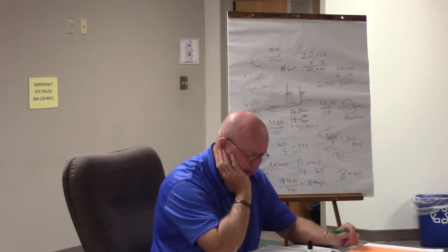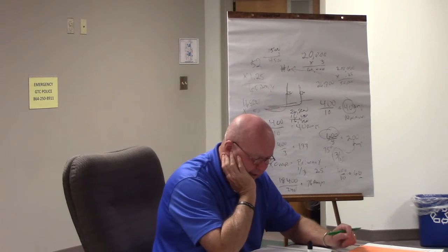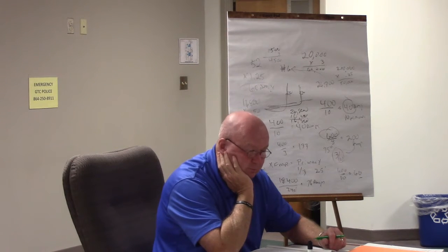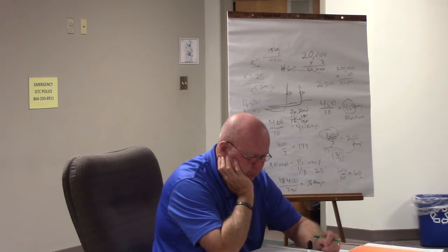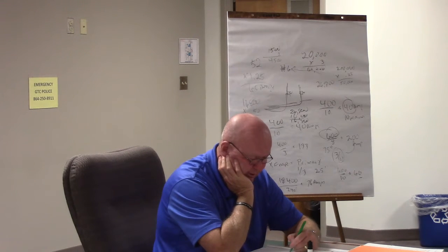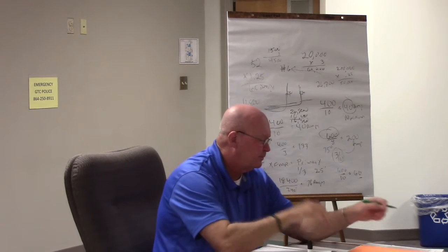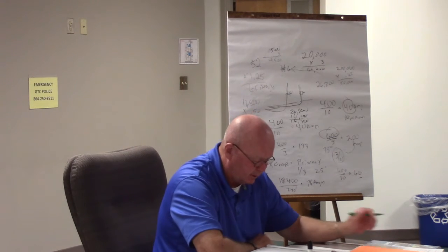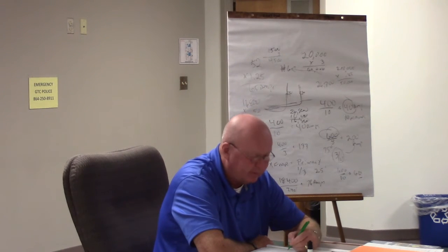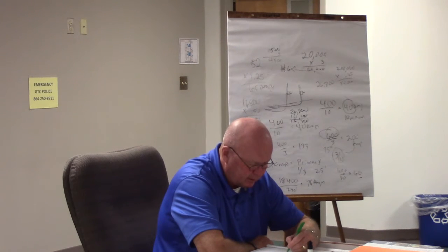Okay. What is the ampacity of a single-phase resistance load with a nameplate rating of 38.4 kW, 240 volt? We have to take 38.4 and turn it into 38,400. Should be 160 amps, which is A, because we divided 38,400 by 240, giving 160 amps.